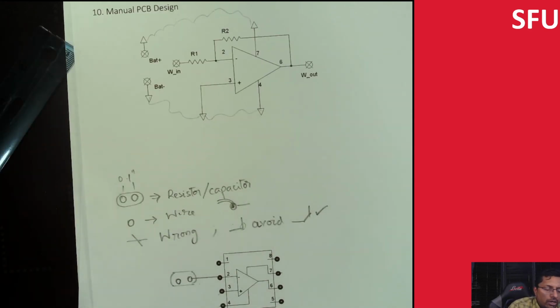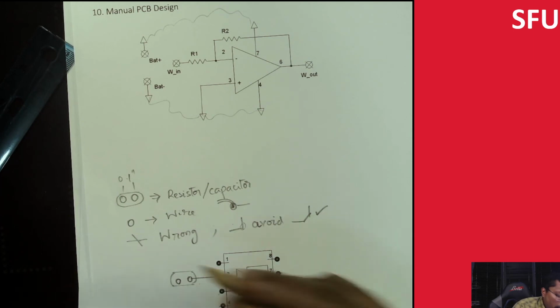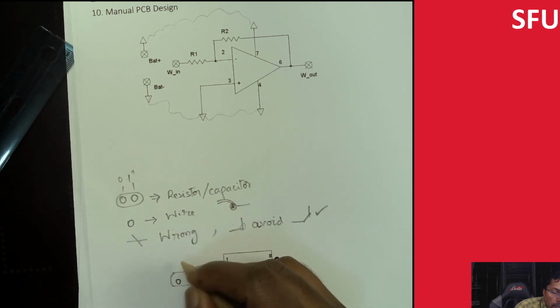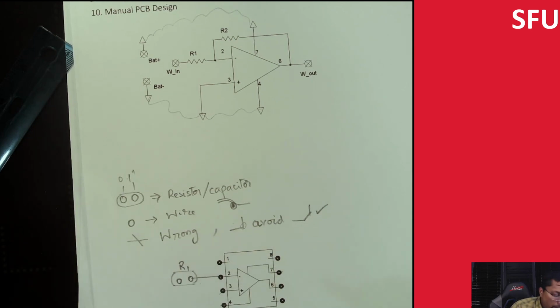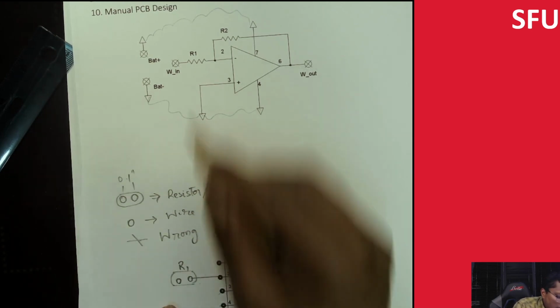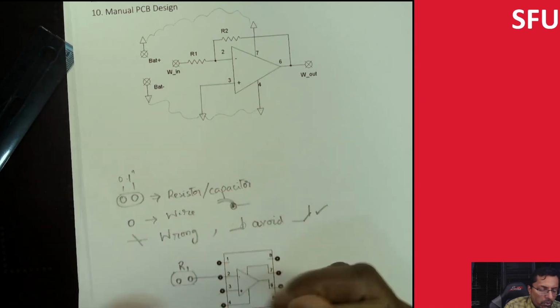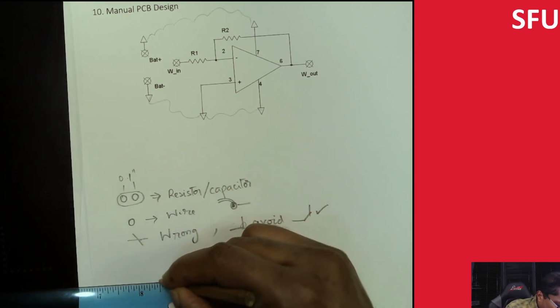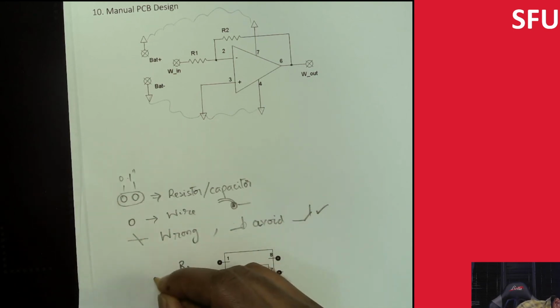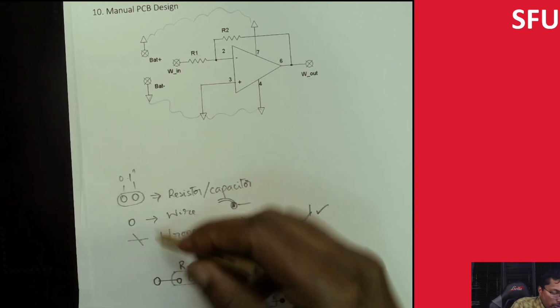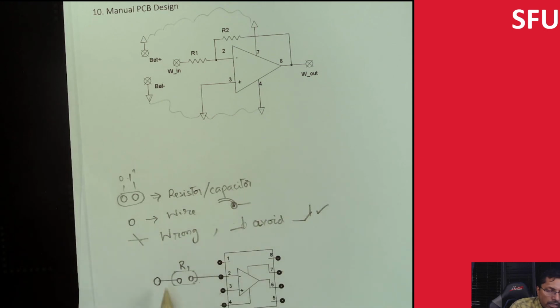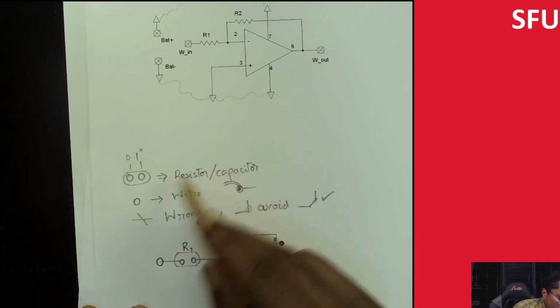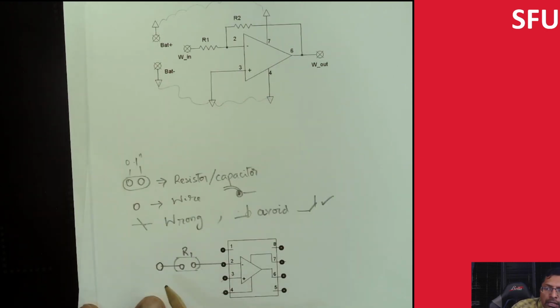Typically in the printed circuit board you have what's known as a mask or a layer where you can actually create letters. If it's a more expensive board, you can have letters. So we'll assume that. This is called R1, and R1 is connected to a wire input. Let's extend this further to create our wire input. It's going to be a simple pad. Then you assume that the wire is connected and soldered at this point over here. This is going to be called W in.